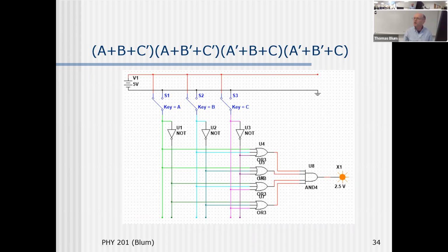If I change the red to orange, it should all change, and that will indicate to me that Multisim understands that they're connected. If they don't all change, then I probably rewire it. And the rewiring has to be done while it's off. I can't rewire it while it's running.